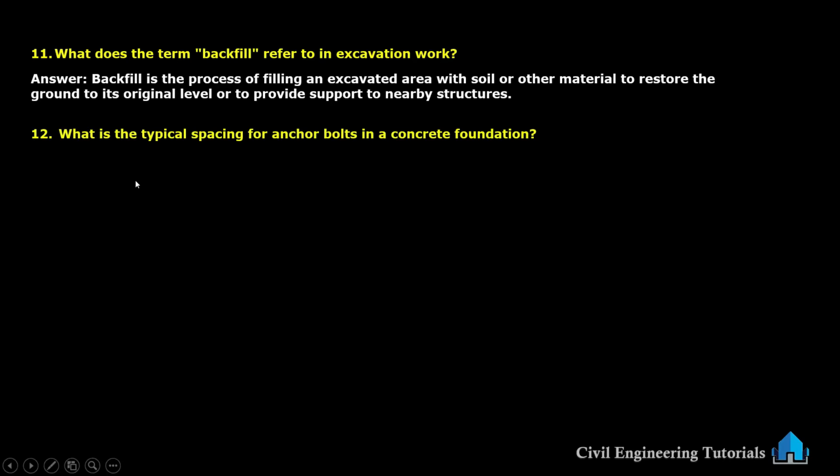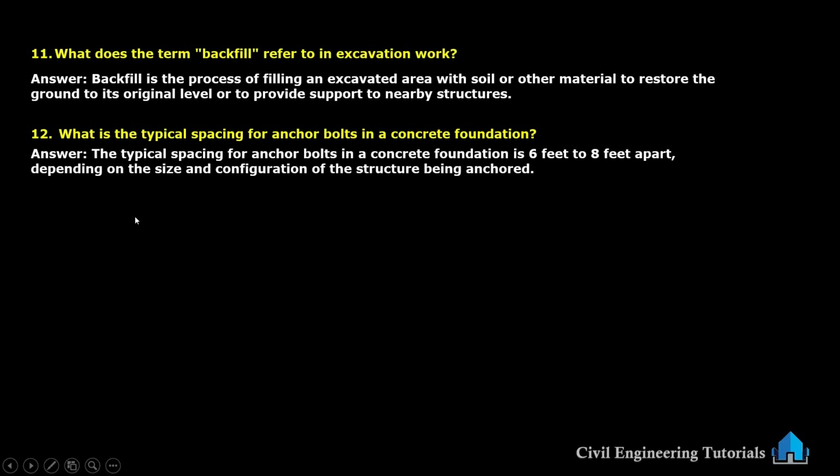What is the typical spacing for anchor bolts in a concrete foundation? The typical spacing for anchor bolts in a concrete foundation is 6 feet to 8 feet apart, depending on the size and configuration of the structure being anchored.